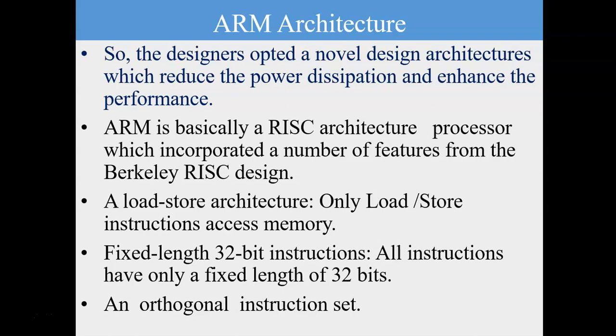That's why, in order not to use more memory related instructions, it uses only load and store instructions, very limited instructions. That means memory access instructions are very few in the case of RISC architecture. That means the speed is automatically improved and power dissipation is reduced. That's the most important point. Remember, whenever we say ARM architecture or RISC architecture, the first thing is load store architecture. Only two instructions, load and store, are available to access the memory. Whereas in the normal CISC, you will have more addressing modes or more memory based instructions. Here, more register based instructions.